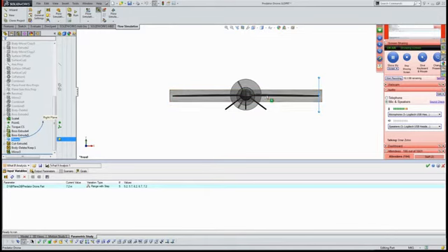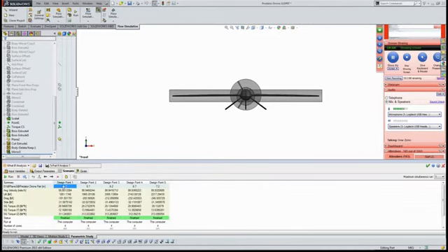Then I'm cutting the wing, and then I'm mirroring the wing to the other side. So it's a way to look at smaller wing geometries, basically. And I'm asking it to run all of these different scenarios for different wing lengths and tell me what the lift is. And you can see, the default here, 7.2, is about 2,200, 5.2 is about 1,800.